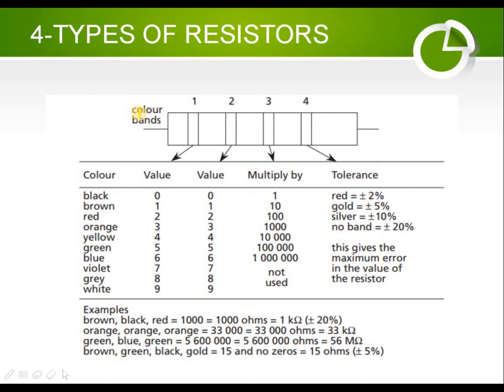Further continuing the topic, this is the method for how we can calculate the value of the resistance by the color coding method. The first band is read by using this table. Everybody should remember this table: black, brown, red, orange, yellow, green, blue, violet, gray and white.